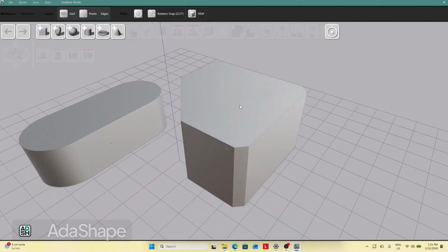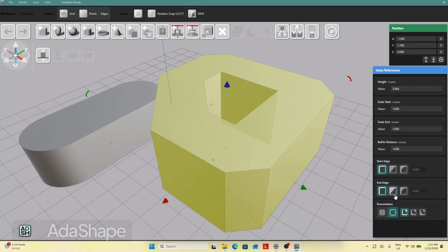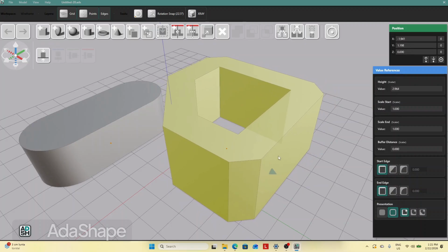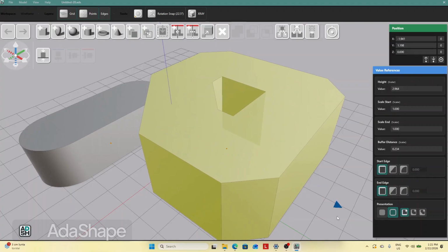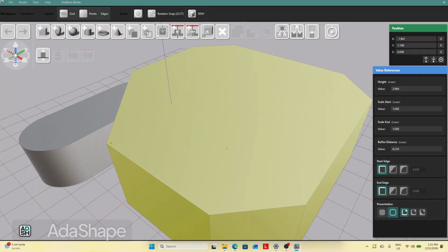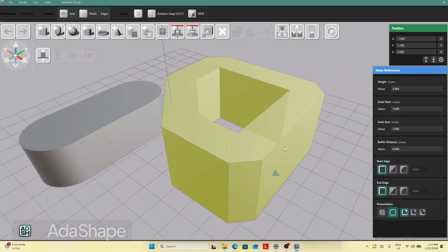We have two types of extrusions. This is what we call solid, and then we have a buffered shape, which basically takes in the lines and converts them to walls. And in this mode, we have this triangular widget down here, and we can pick it, and we can use that to set the wall width. And there's actually no limit. You can even close those walls and convert this to a kind of a closed solid shape itself.